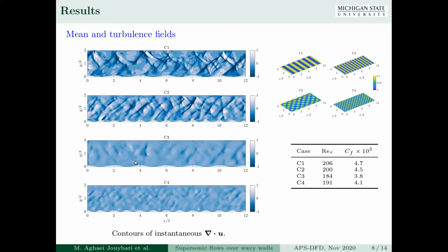But these shock patterns are destroyed in 3D surfaces because of the surface roughness and are replaced by weak shocklets. These strong shock patterns in 2D surfaces impart a considerable amount of irreversible heat generation, and that's why the temperature profiles are higher for 2D cases compared to the 3D surfaces.